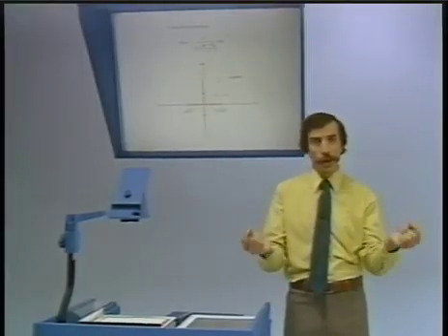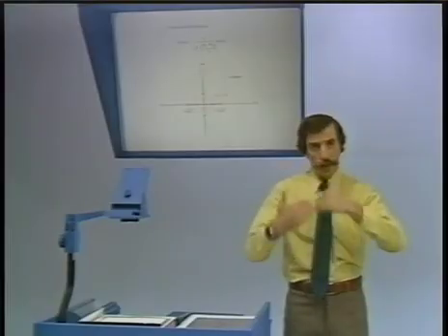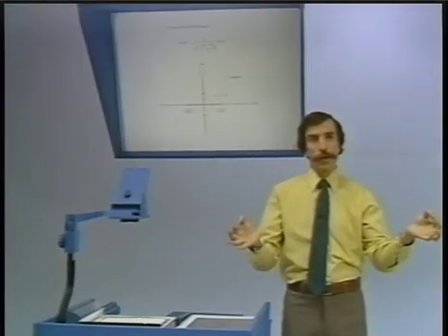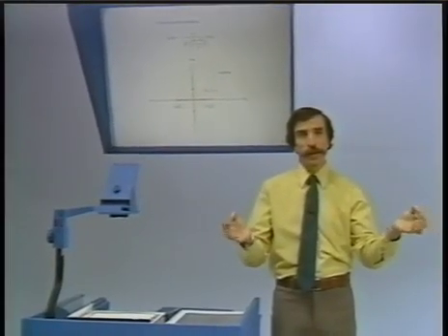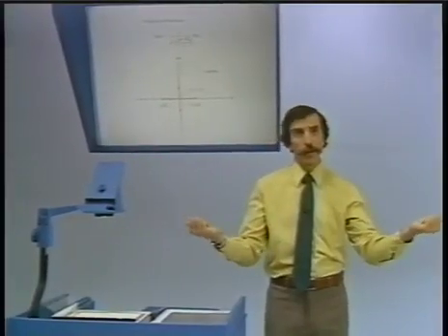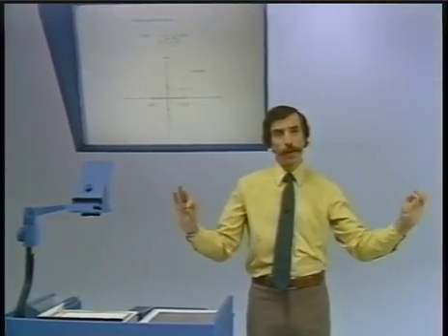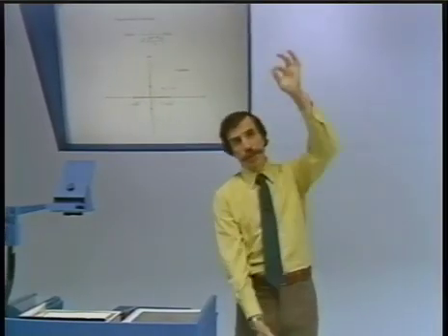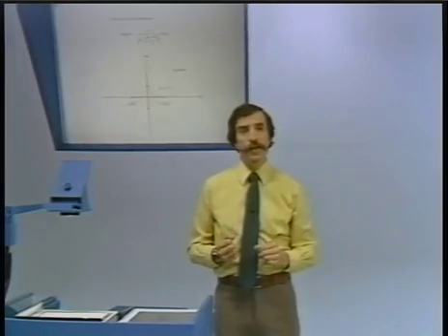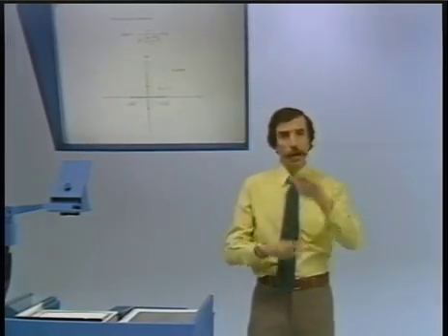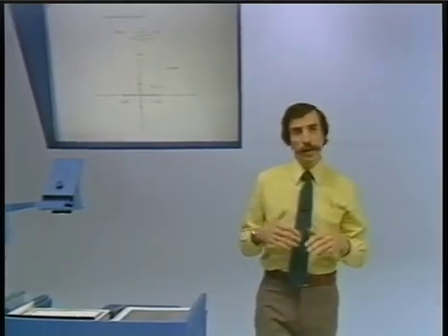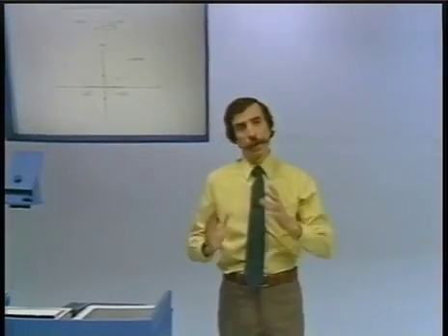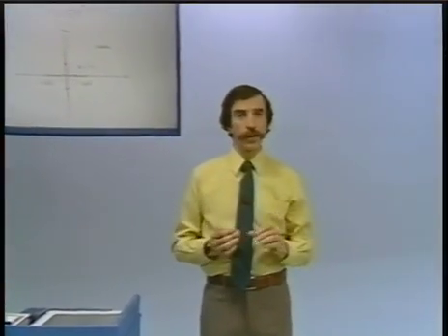see is that with the open loop system, as we introduce feedback, those basic poles move in the S-plane, either this way as k1 becomes more negative, or for this particular case, if k1 is positive, they move in together, split, and move along the j omega axis. And that locus of the poles, in fact, is referred to in feedback terminology as the root-locus.